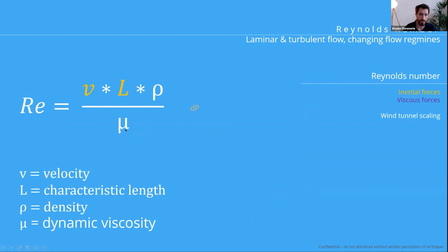The Reynolds number is also something which is quite important. This is not a real physical quantity. Very often you get asked, how do I calculate the Reynolds number for this application? Well, we don't know either because it's arbitrary. The reason being that you need a velocity. Usually this is the free stream velocity, but if this is a local velocity around a small wing, which is on a bigger car, then what is your velocity? The length is a characteristic length.